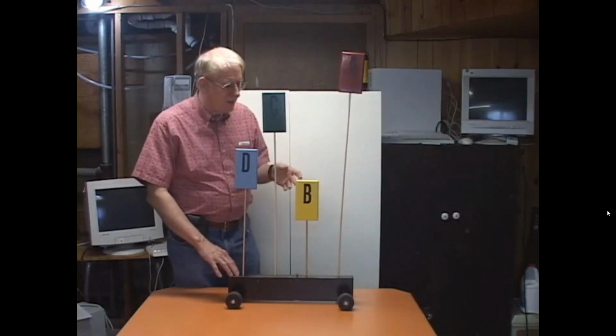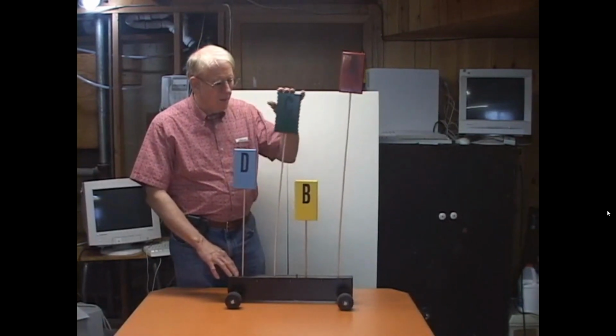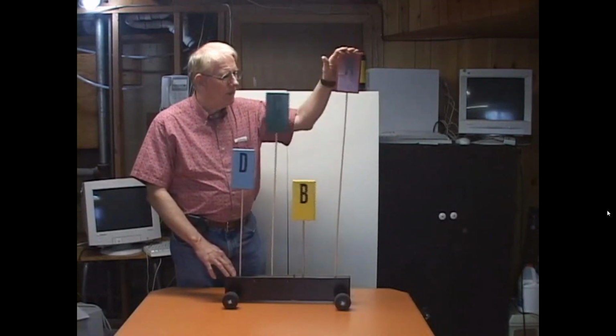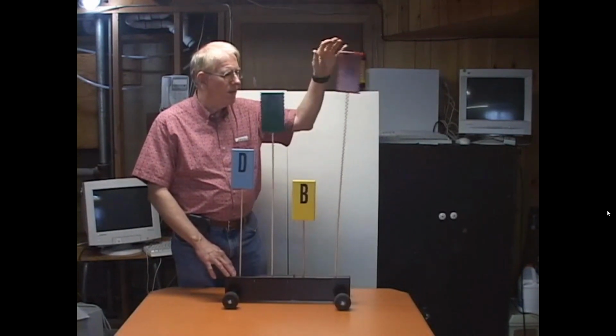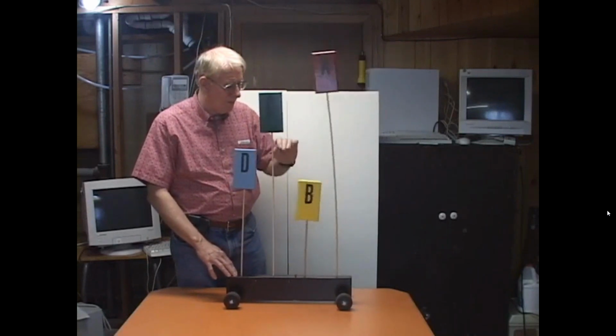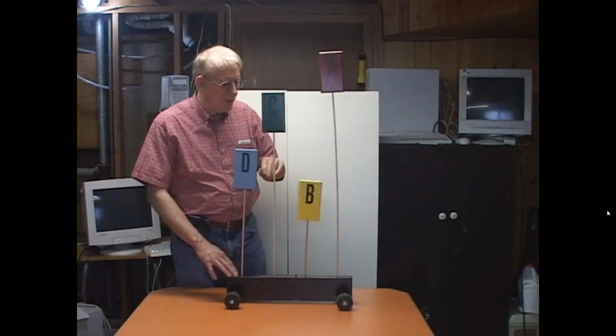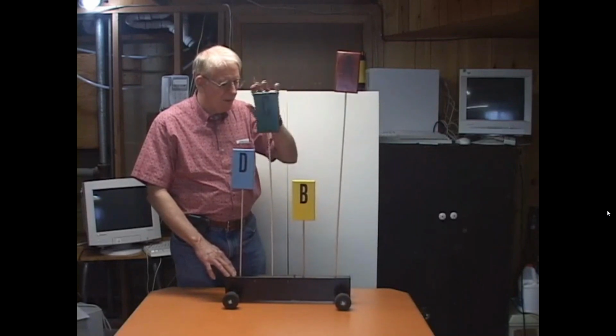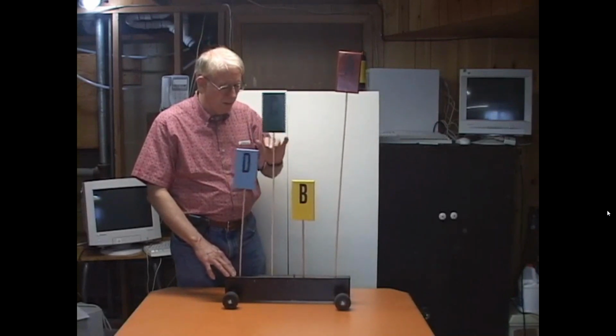And so then I explained that, well, it actually has to do with the resonant frequency of each of these buildings, which is quite different. The resonant frequency is the frequency the building wants to move back and forth. You just give it a bump. You can see the short building moves back and forth very quickly when you just pull it and let it go. The tall building is very slowly. And you move with intermediate frequencies.